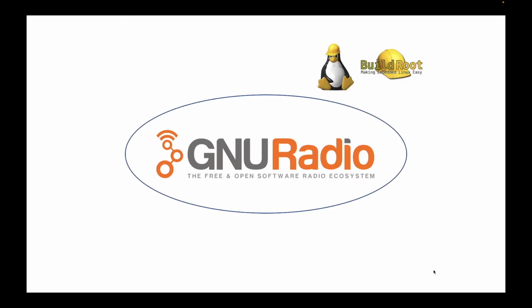Buildroot is a collection of makefiles and patches that simplify and automate the process of building a complete bootable Linux environment for an embedded system. It will allow us to generate a Linux image implementable on the Raspberry Pi 4. For Buildroot and GNU Radio to work properly together, we will use our teacher's GitHub folder.